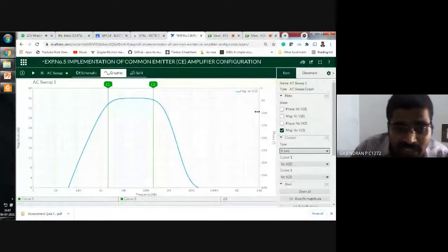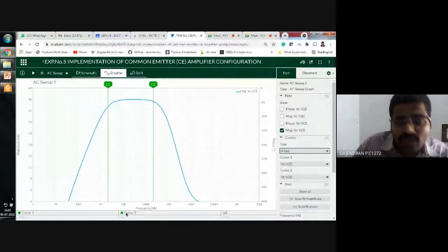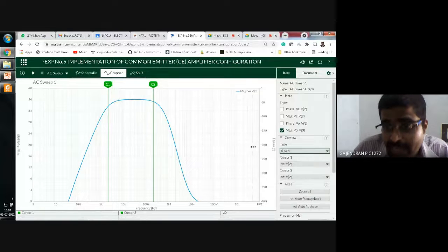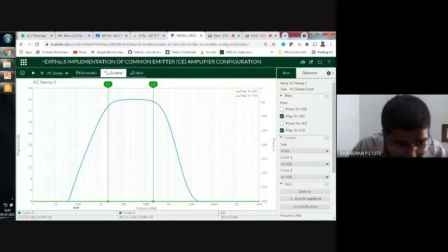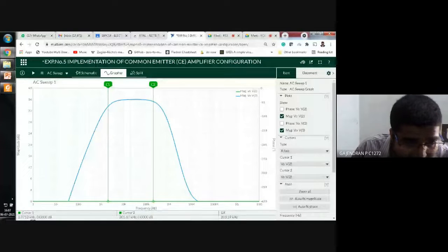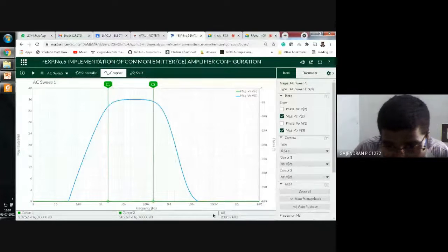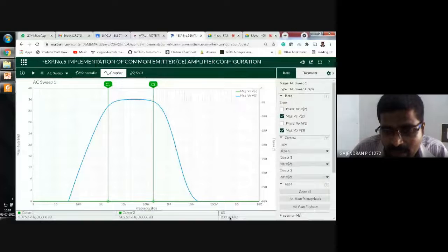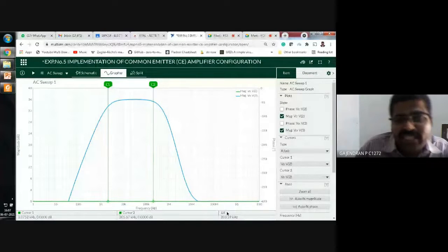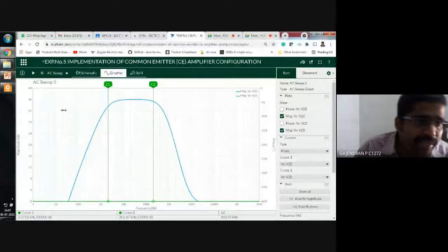See, and one more thing, there will be some reading under that. We are unable to watch that. So for that purpose, we are going to do one thing. It is at the bottom. I need to bring the reading little up. Thereby, I am going to click this magnitude also. Now everyone closely watch at the bottom of the window. You can view the cursor 1 decibel value, cursor 2 decibel value, and the change in the frequency. Can you see it at the bottom, please? Can you see it? In the end I am going to show it in the PPT in a clear way.